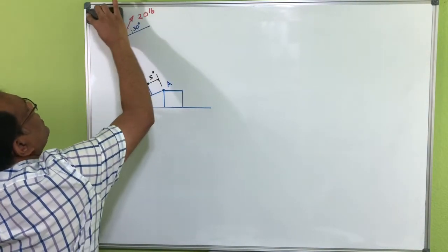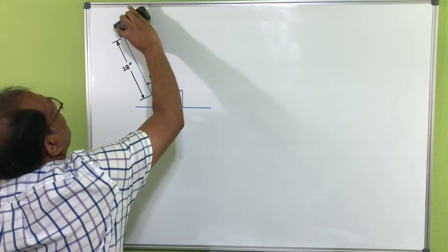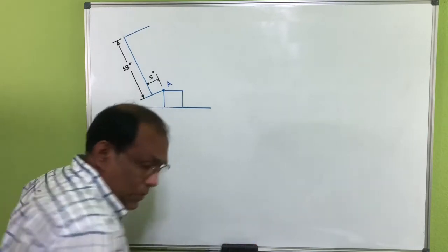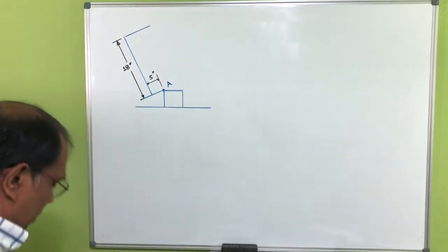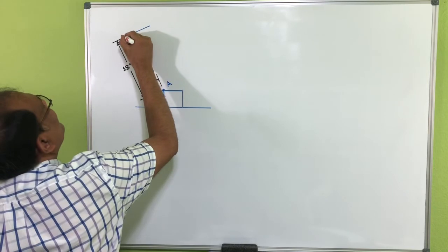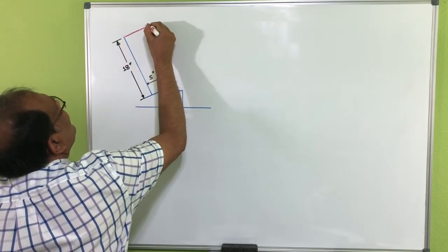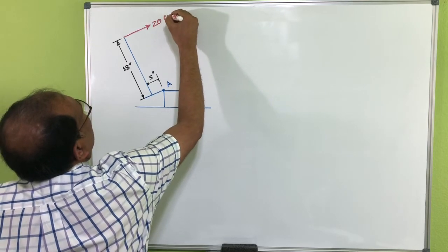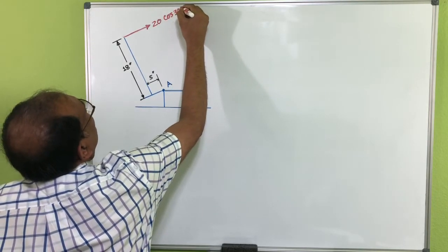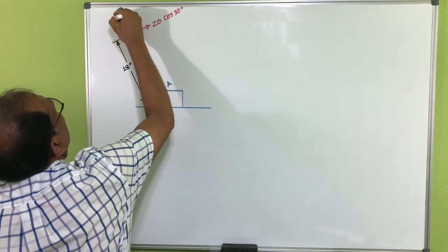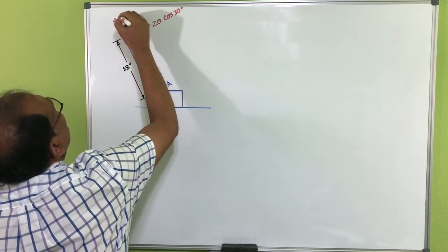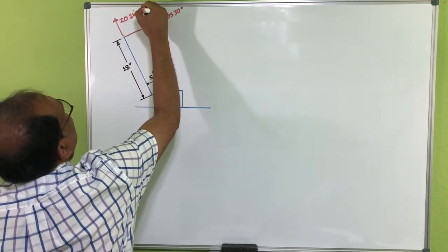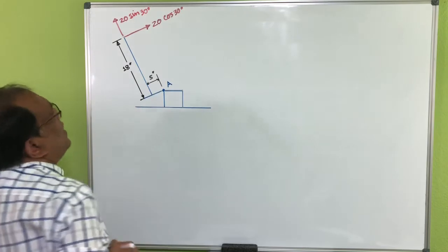Okay, so to do that, let's try to resolve that force, 20 pounds. So this one has to be 20 cosine 30, and this one has to be 20 sine 30.